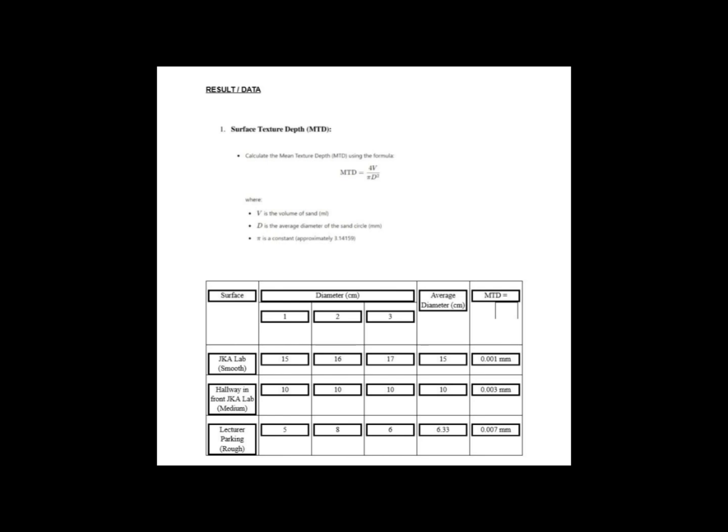This shows that when spreading the sand, it is very hard for the sand to spread because in between the surface there are a lot of spaces where the sand does not spread, but it fills in the gap first. This shows that the rough surface is rough, obviously, but it shows how this sand patch test can represent the roughness of any surface just by spreading the sand.